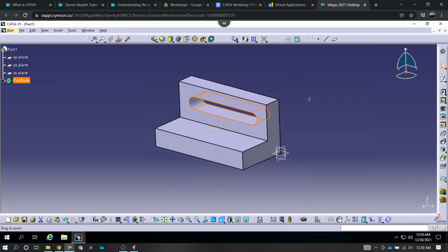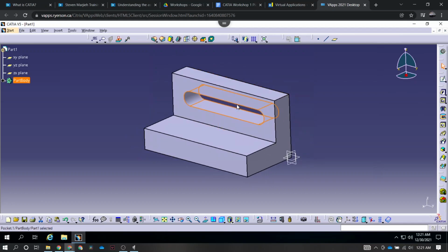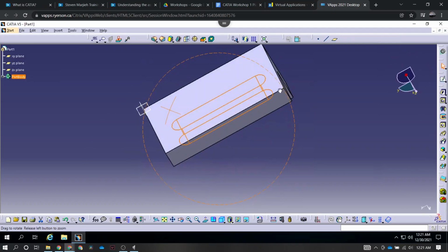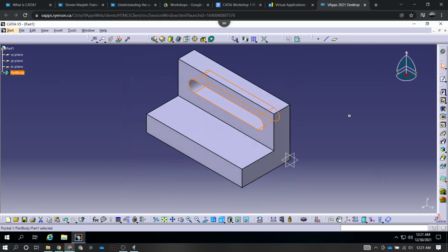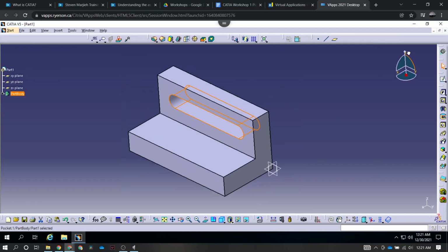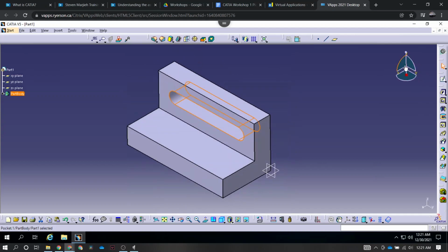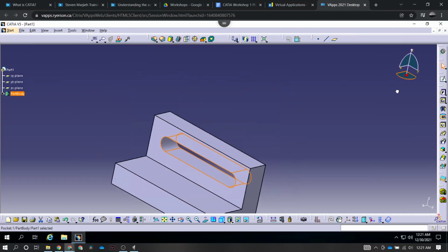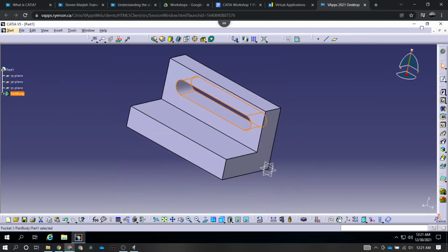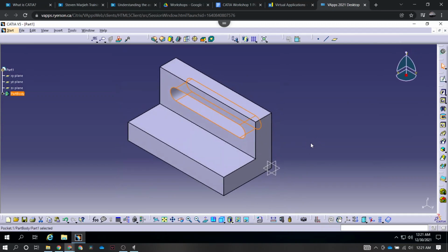Okay, so it tells you how to zoom on things. You just press Control, middle mouse button, then up and down on your mouse, right? But to rotate, you actually do the opposite. So middle mouse button first, Control, and then you move things around, sort of like that, right? And you can always go back to your isometric view just like that. Another way to rotate is to use this little sort of plane thing, axis thing that you can move around. If you click on the plane, it drags on the plane. Click on the line, goes up and down the line. I don't like to use those. I like to use the mouse shortcuts.